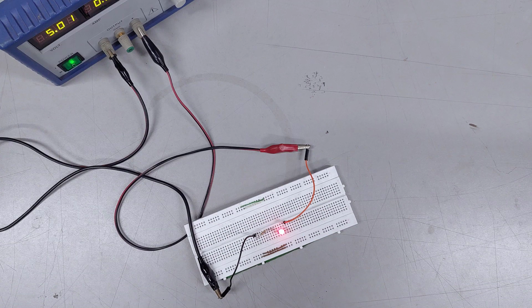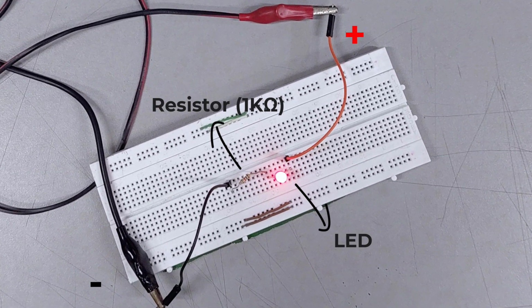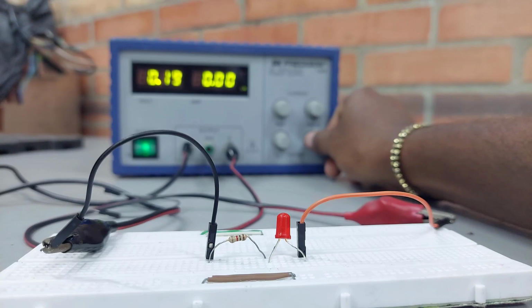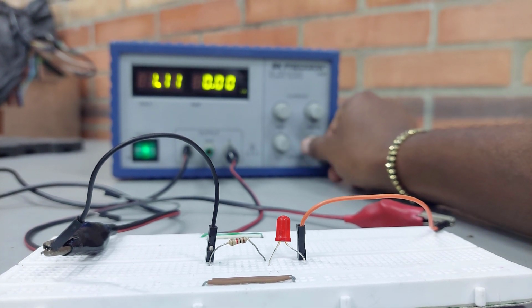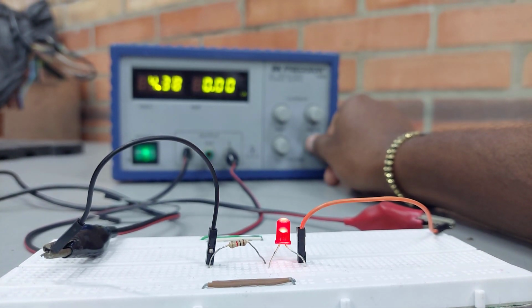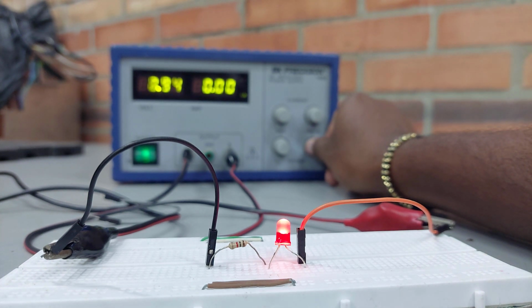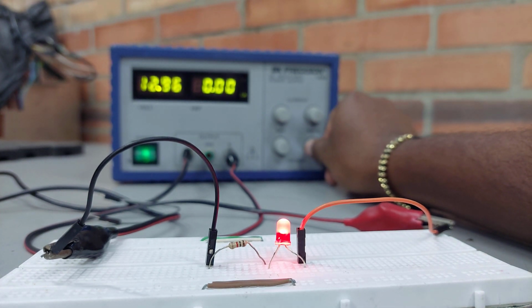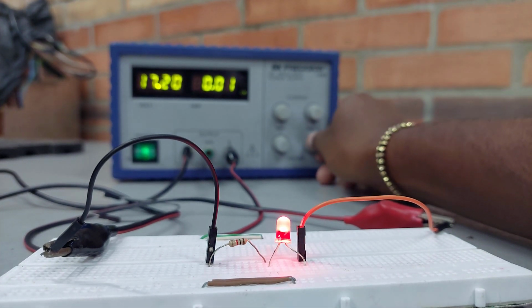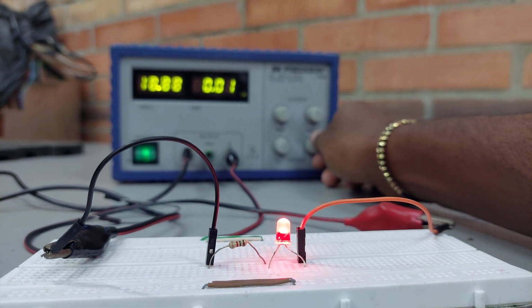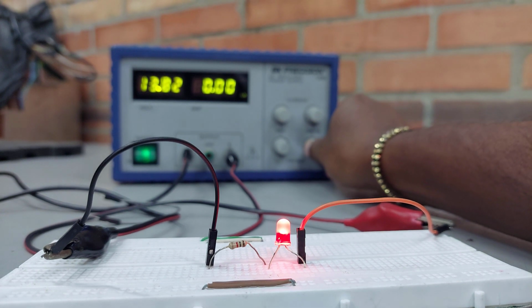Now that we have reviewed Ohm's law theoretically, let's take a look at how it looks in real circuits. In this first circuit, I have a power supply connected to a 1000 ohm resistance and a red LED. So if I increase the voltage and I keep the resistance fixed, according to Ohm's law, the current will increase, so the LED lights up brighter. And inversely, when the voltage begins to drop, so does the current and the LED will dim its light.